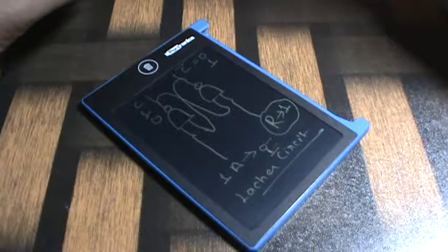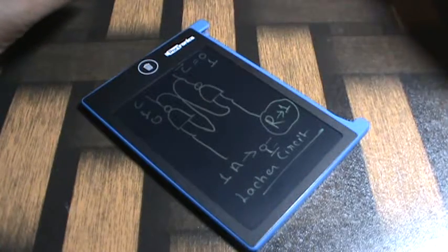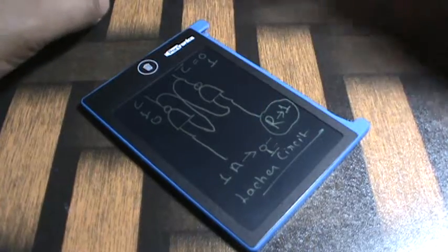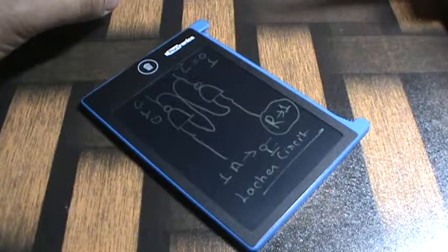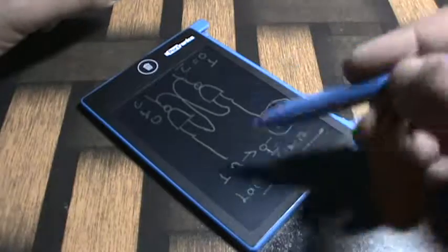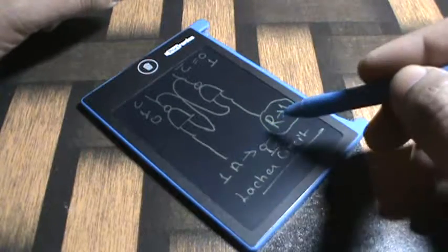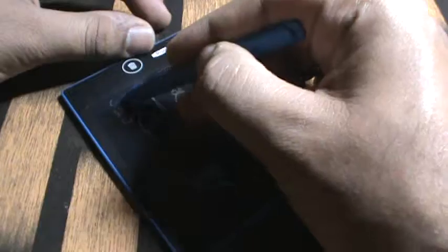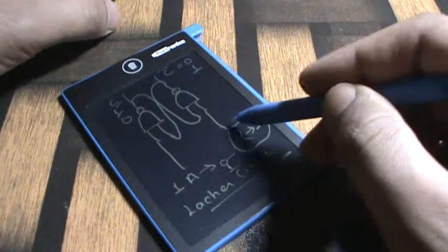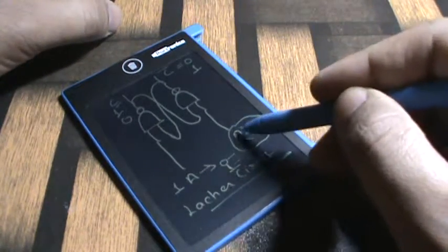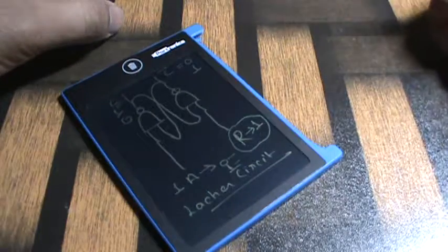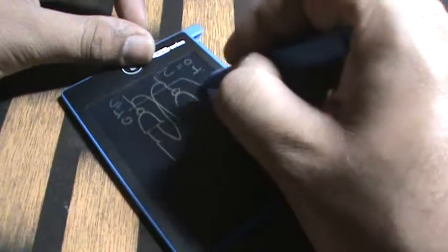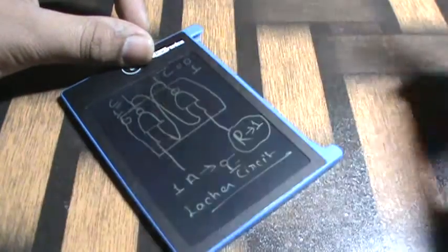Basically what we require is to save the value of C, and in this circuit, when we change the value of A to 1, the value of C becomes 1. That's all. Afterwards, if we change A to 0 or 1 or anything, it doesn't matter to C. It remains 1 until we change the reset pin, or R, to 1. If we change it to 1, this becomes 0. Now let's say we compile this and put this thing into 1 unit.